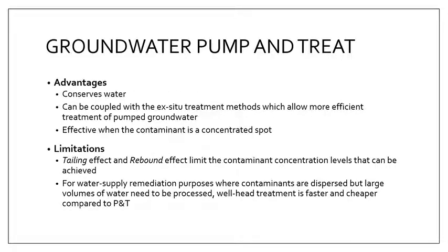Now, the advantages of this method is that it conserves water, and also the ex-situ or off-site treatment methods allow you to more efficiently treat the water, meaning you're just directly dealing with the contaminated water once you take it to the surface.